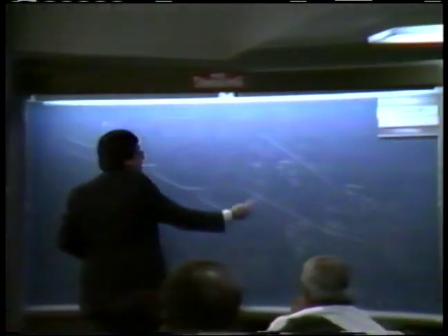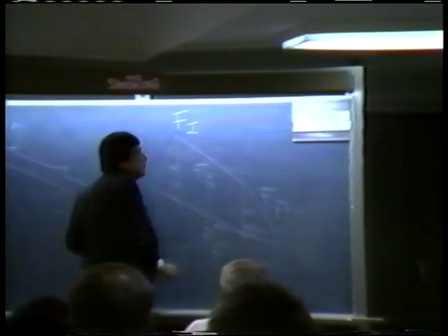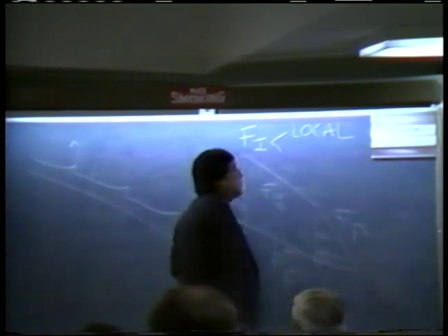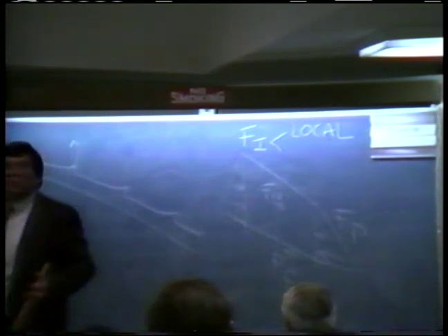So inertia, I can't picture it in there. I'm going to put it in here. But the inertia has two components. It has a local component by virtue of the inertia itself, and it has a convective component because of the fact that we are very conveniently choosing to stand and let the flow go by. To stand in a certain place and the flow is going by, and that's called the Eulerian presentation. If we, on the other hand, were traveling with the flow, then there would be no convective inertia, and we just had local inertia to contend with.